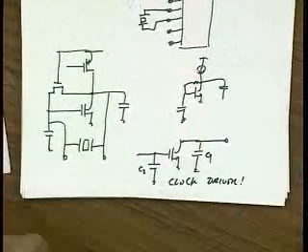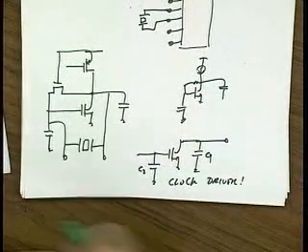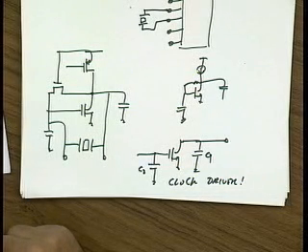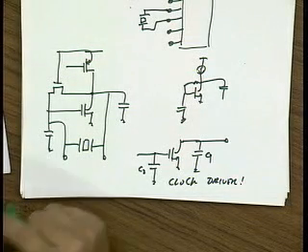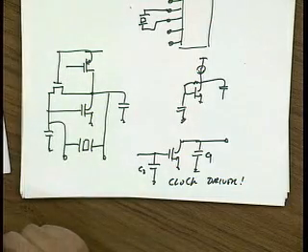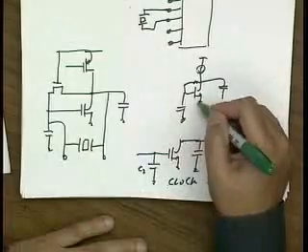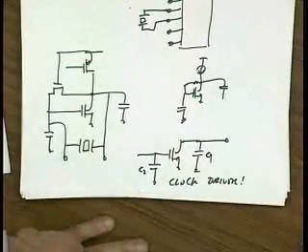Okay? Questions? Yes? What is the MOSFET in feedback for? What does the resistance do? That's just to bias it up. Because it's a self-bias configuration, so it's a diode-connected MOSFET device.